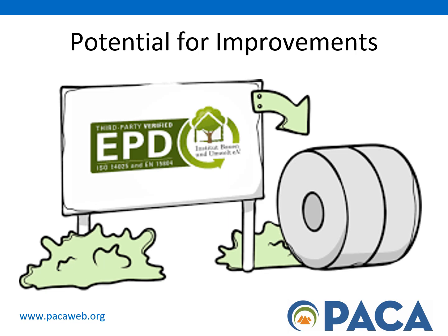As always, there is a potential for improvement. There are opportunities to reduce the environmental impact of concrete by using alternative materials, such as supplementary cementitious materials like fly ash, slag, and silica fume. Also, advances in production techniques, carbon capture and storage, and the use of recycled materials can significantly lower the environmental footprint of concrete. Another option is Portland limestone cement, which allows between 5 and 15% of limestone in the clinker for cement production.